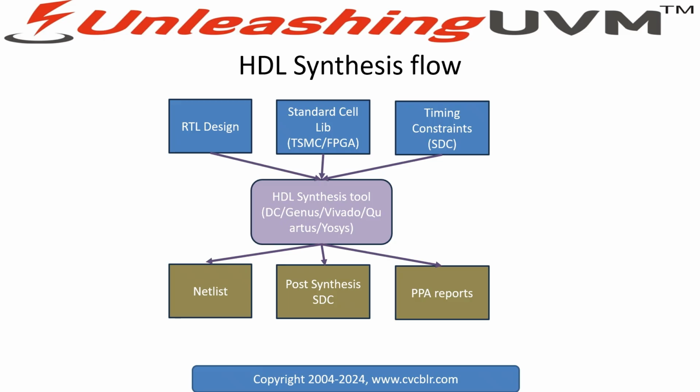But a lot of techniques that we talk about in this whole training are equally applicable to a post-synthesis SDC as well. Because the design signal names could have been changed, some signals may be gone, there's a mapping and all that stuff. So a post-synthesis SDC is as good as a pre-synthesis SDC for us from a pure verification perspective. In fact, the post-synthesis netlist goes along with the post-synthesis SDC. And of course, you also get a PPA report. PPA stands for power, performance, and area, and you want to know whether you met all your constraints. That's the typical HDL synthesis flow.